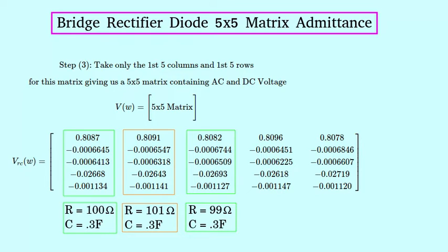The fundamental harmonic is very low, but not zero. This is convenient because zero values here would give us a non-invertible matrix, which we couldn't use in this program. The ripple is contained in the second frequency, which is low, but much larger than the fundamental harmonic, which is expected for a bridge rectifier.